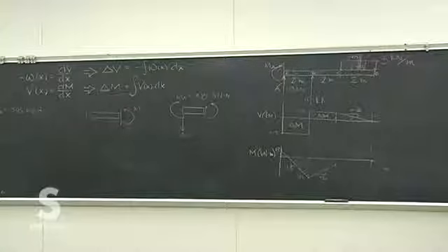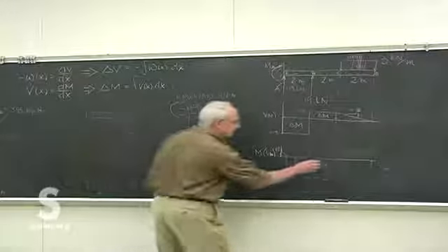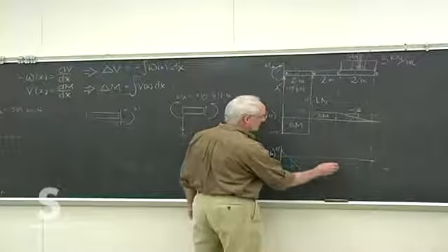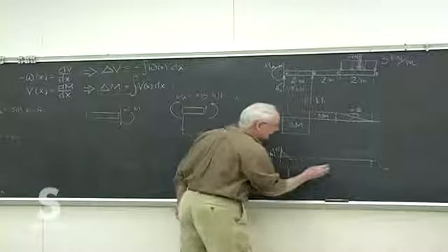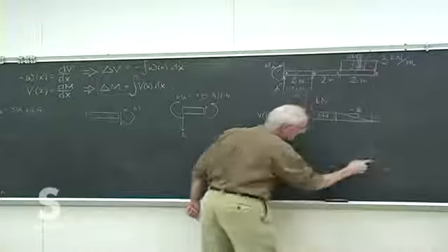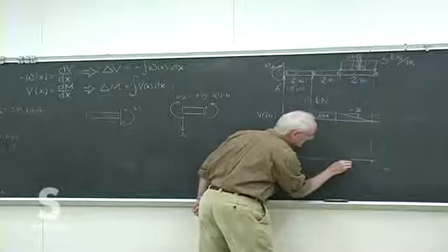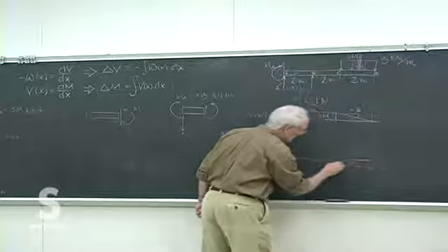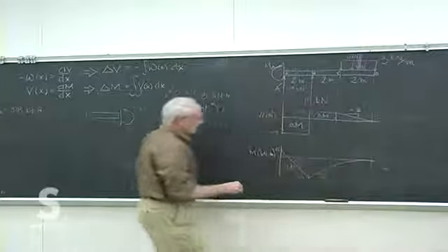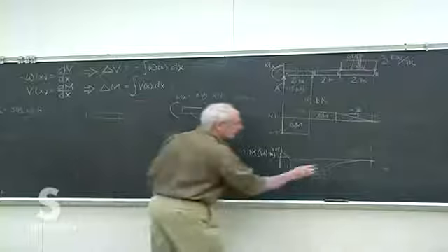So we didn't have to actually do any imaginary cuts, didn't have to break any of them in there. And then, yeah, you know how it finishes. Slope is continuous. There's no break in the slope here, no break in the curve itself. There's no applied load. And we know we finish at a 0. So continue the slope, but then start curving it in and bring it in to the final little bit.